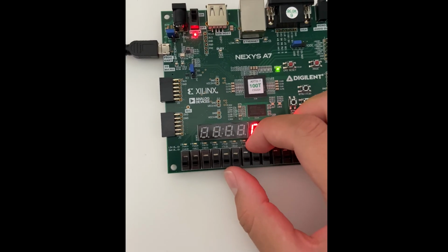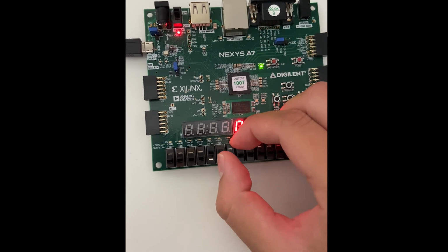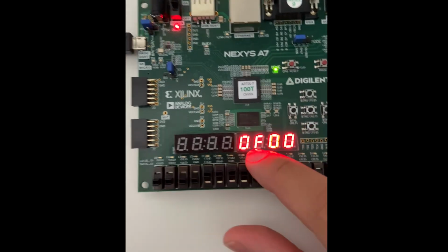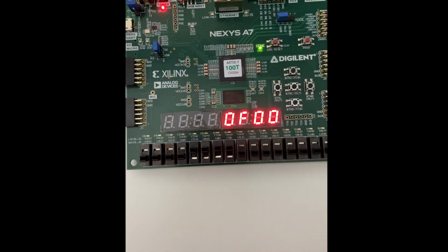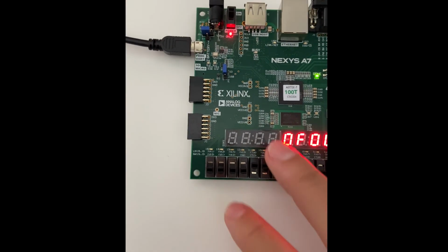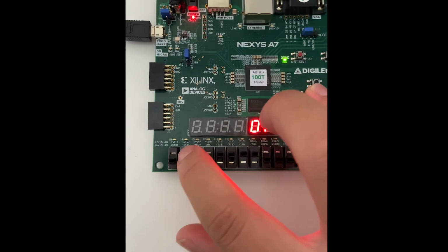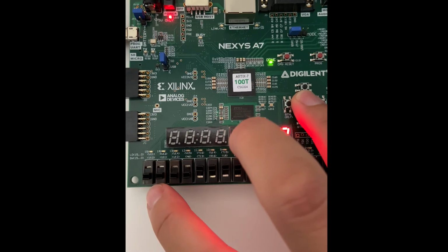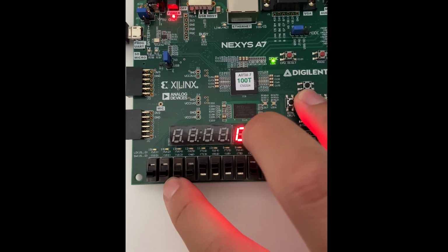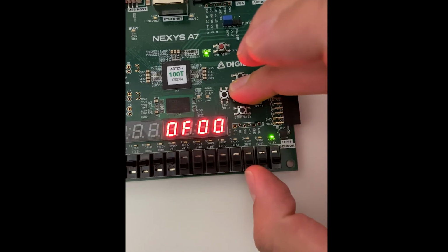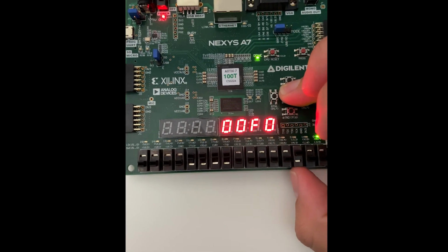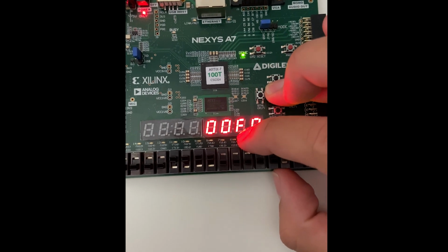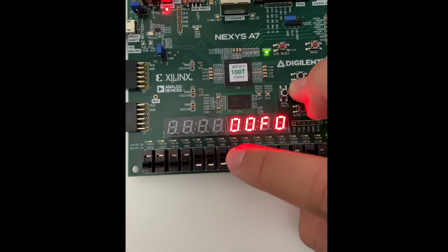Okay, so now I'm going to start passing in values to the input of the barrel shifter. Just for ease of use, I'm going to pass in F to this second MSD value right here on our 7-segment display. And now I'm going to toggle into register 1, and we're going to start changing values. So now we're in manual, no load, shift right, and I'm going to shift 4 places, and we can see here that F is now moved over 1.